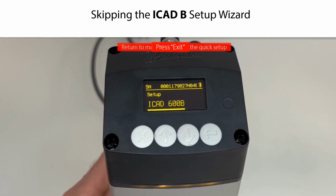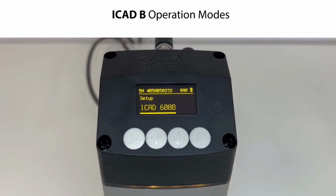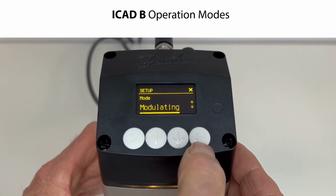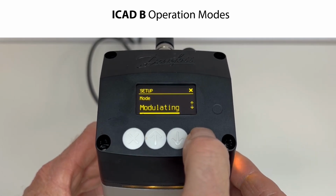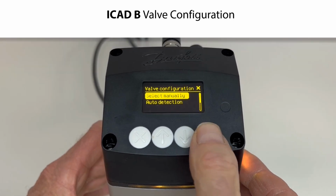Therefore, press exit to return to the main screen and the setup wizard. Press enter to start the ICAD B setup wizard. The first step is to specify the operation mode, which as default is modulating operation. In this example, we keep this and confirm by pressing enter. Please see more details about operation modes in a separate ICAD B setup and configuration video.